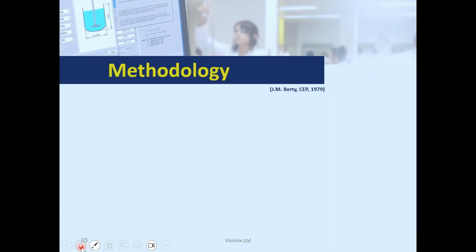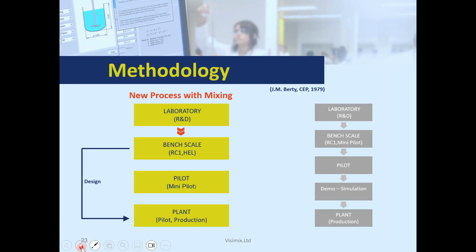Okay. And of course, we discussed the proposed method. The main idea in the proposed method, let me show it to you, was to connect the data we know from the lab, so for any deviation we can experiment, with the equipment we will use, and try to set up the equipment with mixing parameters that will generate the same interaction between the materials at the smallest scale possible, in order to be sure that we are evaluating the process in the same range of work that we will meet in the production step.